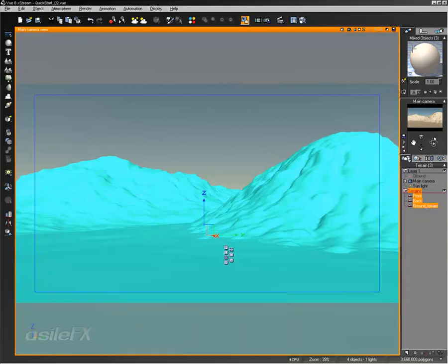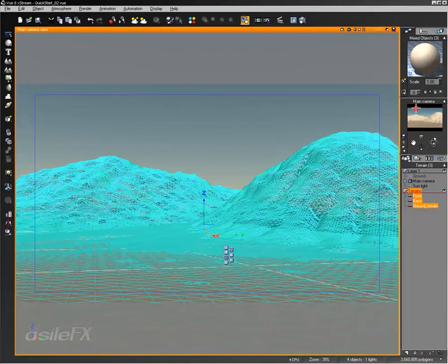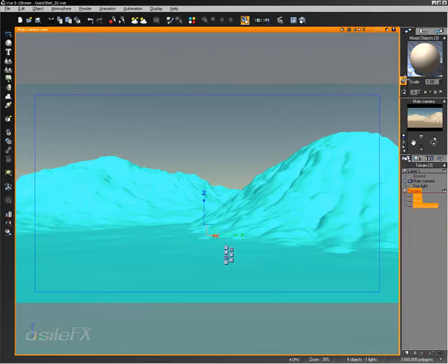So what we can do is up here in the Aspect tab, there's an option to load a material, lower right hand corner. Not all the way down, because that's your preview options, where you can change the display of these objects. You can also hide them when they're not selected, and lock them as well. We'll go back to smooth shaded, but we're going to click on this little checkered sphere with the arrow to load in a material.